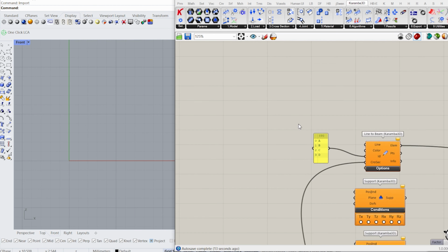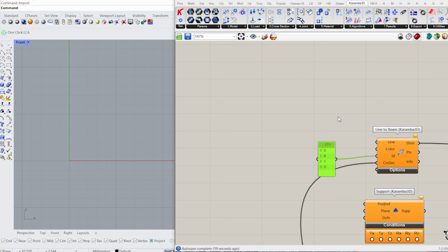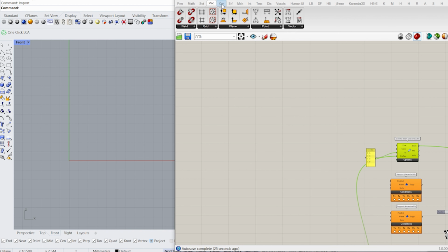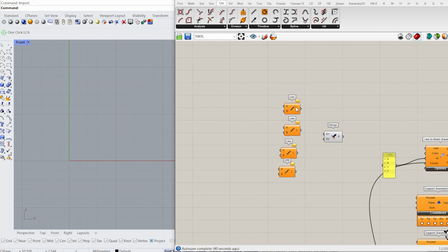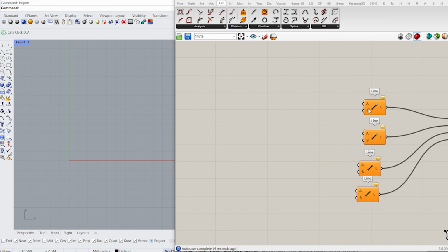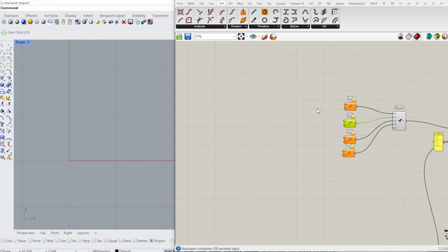Now let's assign the important lines and make them parametric. Let's go ahead. So now for the lines, I'm going to need the native Grasshopper components, and the model is a combination of 4 lines that are going to be assigned in one list. Yes, and now these line components need the start and end point.